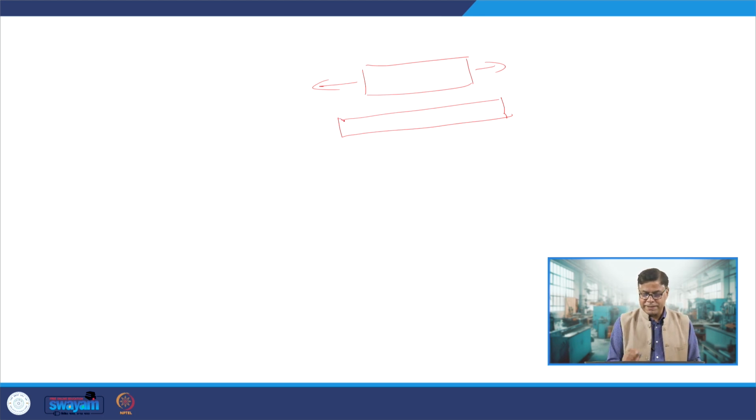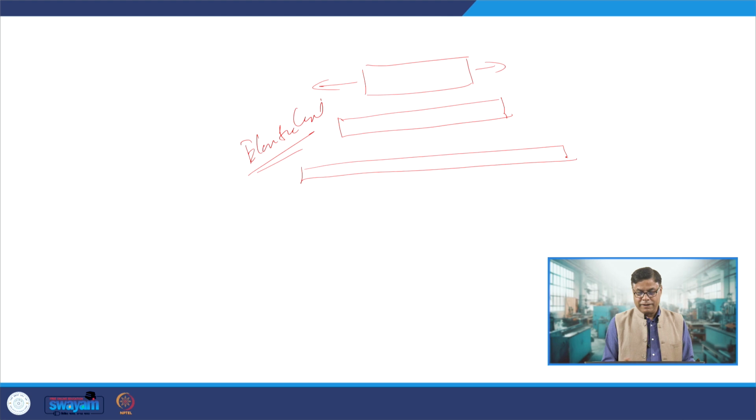So this is the first stage, the elastic limit. On further increasing the stress level, there will be further increase in the length and reduction in diameter, also spread all along its length. So beyond the elastic limit, there will be yielding.